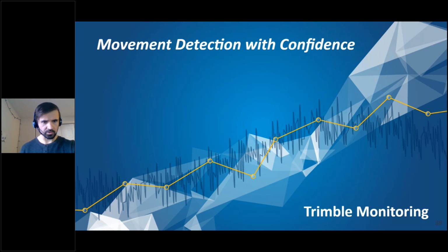Chris asked a question regarding coordinates. Can monitoring be done in local coordinates, or does it need GPS coordinates? Well, I guess yes is the answer there. It can be done in local coordinates. So as long as it's got an XYZ, you can do monitoring with it. Doesn't matter whether it's in absolute or in local coordinates.